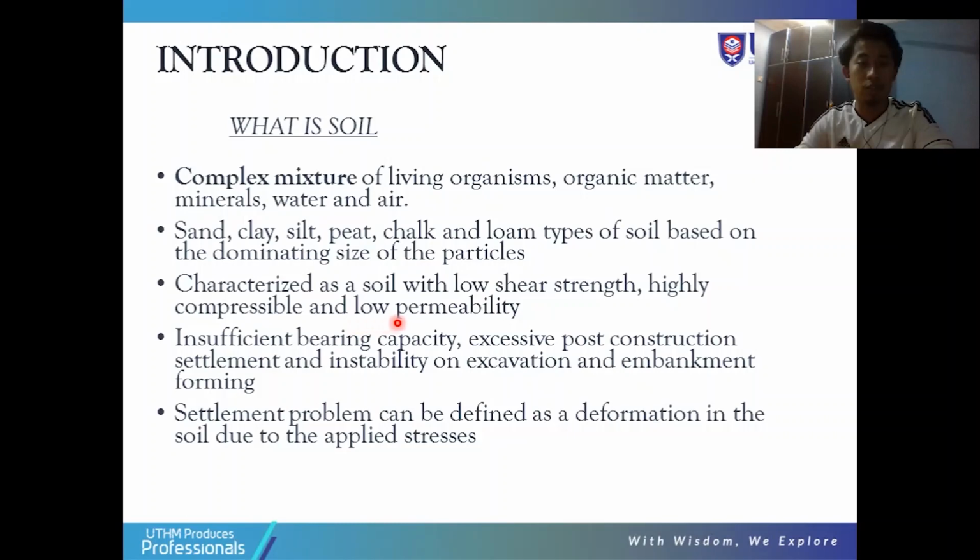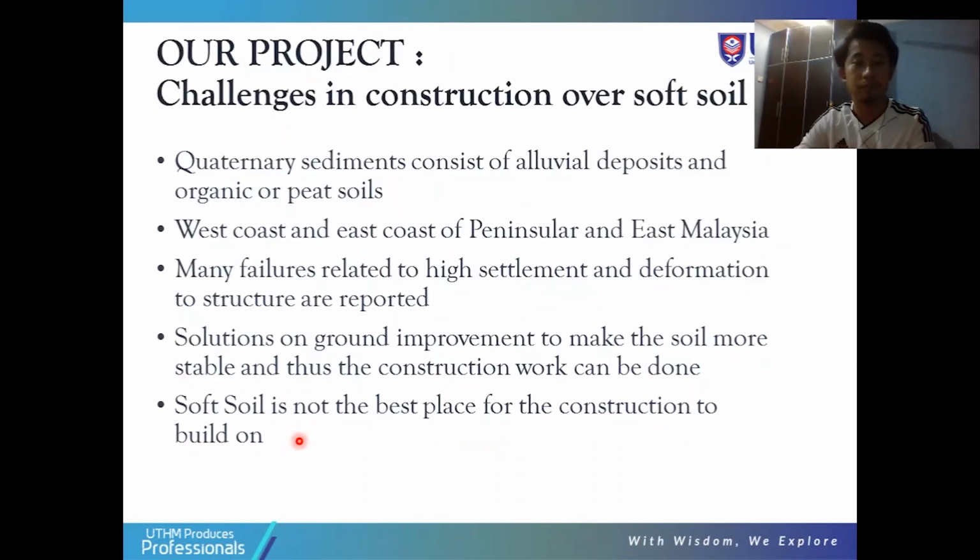The soil is also in a condition of insufficient bearing capacity, excessive post-construction settlement, and instability on excavation and embankment forming. The settlement problem can be defined as a deformation in the soil due to the applied stress. So, the topic of our project is challenges in construction over soft soil. Soft soil is a quaternary sediment consisting of alluvial deposits and organic or peat soil.